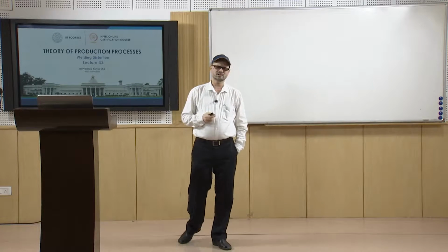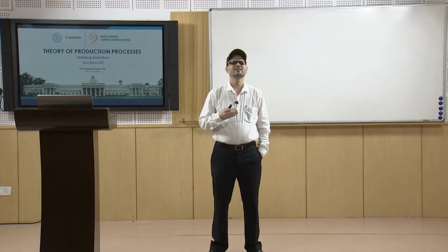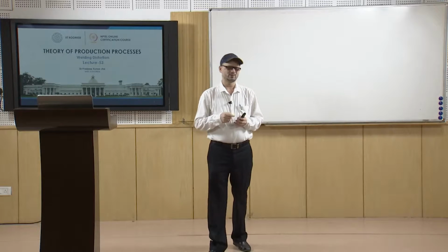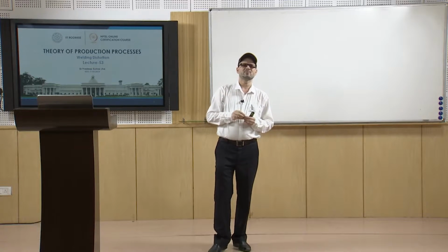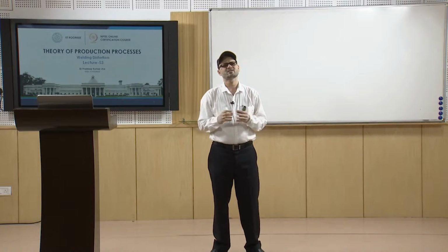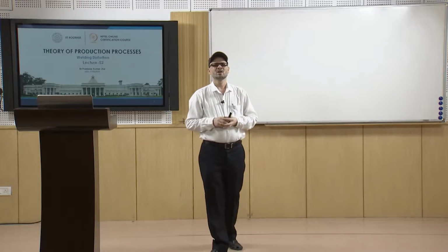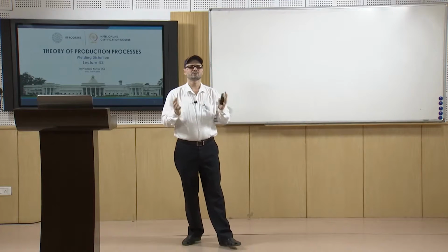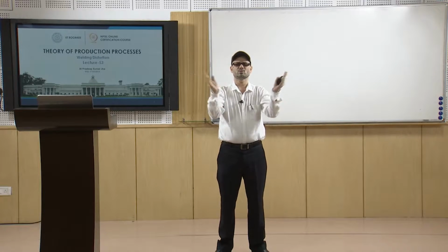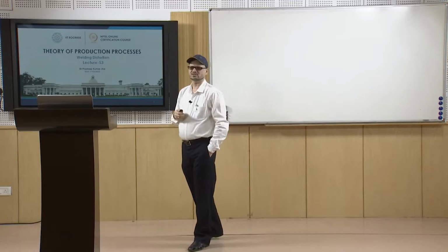Depending upon the structure or the type of specimen you are welding, you will have different types of distortion in the welded specimen. When we are welding in a certain direction, there may be distortion in that direction, or it may be in the transverse direction, depending even on whether the sheets are thinner or thicker. Or it may sometimes bow down, or it may be a rotational type of distortion, it may come closer or it may go apart. Depending upon that, you will have different types of distortions that we will discuss in this lecture.